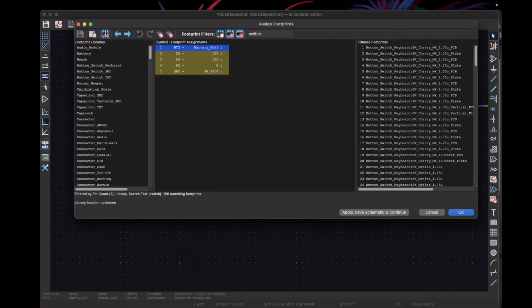Sorry, what is a footprint? So a footprint is like the actual, all of these are footprints on here, and that footprint matches the pinout of the part that you're sticking on there. So yeah, like the physical dimensions for it. For this battery connector, the footprint was this pattern that had the two holes that matched up with the battery terminals that came down.